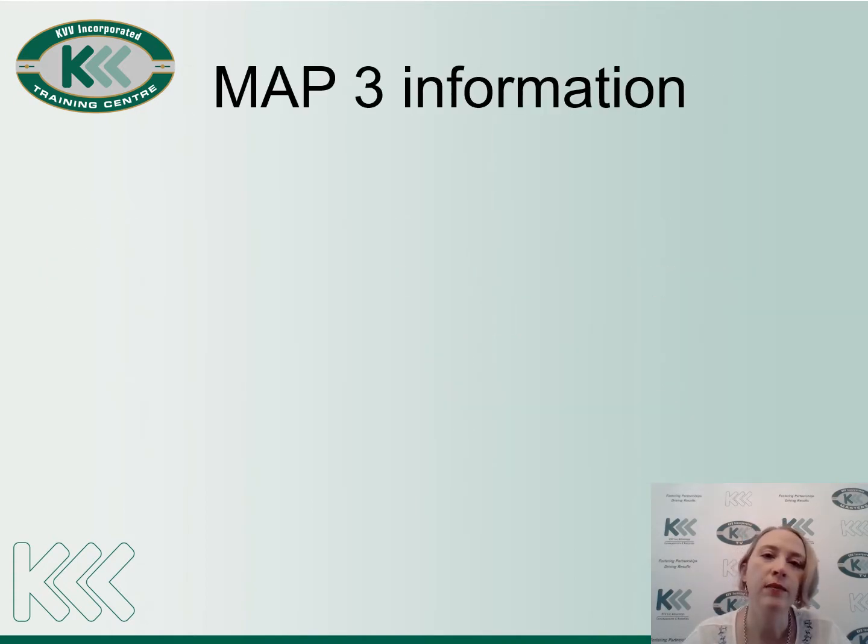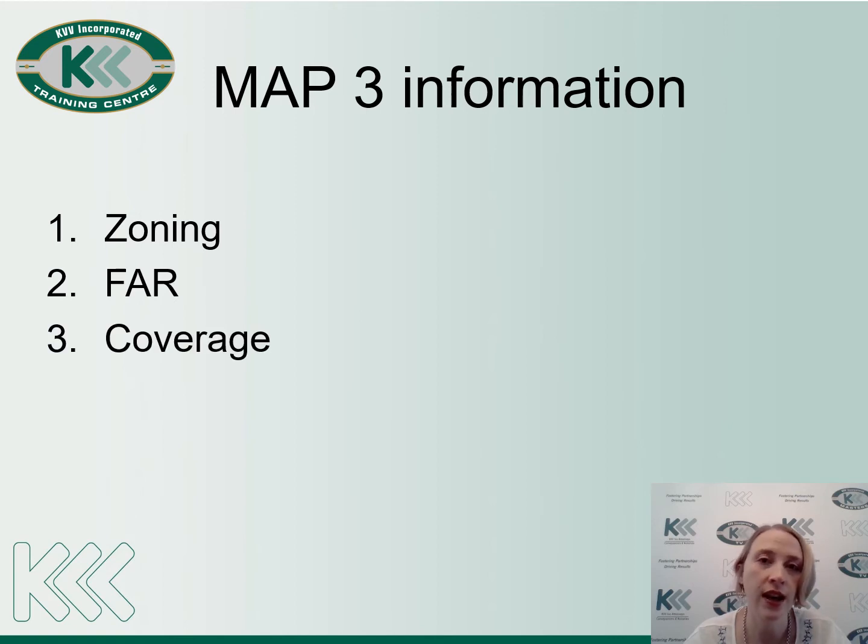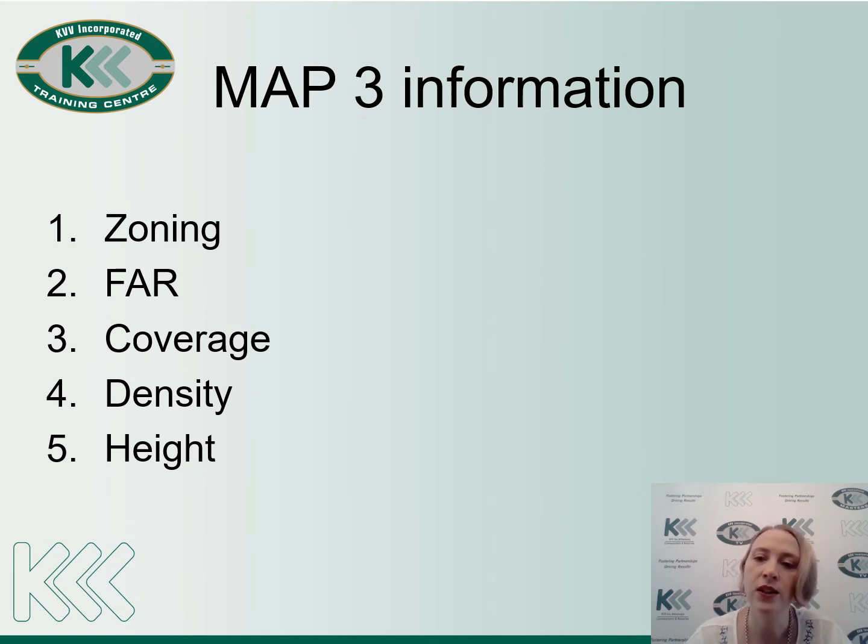Now let's look at the town planning process. Every property in South Africa falls within the jurisdiction of a local authority. At the local authority, we'll be able to see all the information that tells us the identity of the specific stand. In terms of the information at the municipality, we'll be able to see the zoning information, the floor area ratio of the property, the coverage that's allowed on the property, the density allowed, as well as the height restrictions applicable to the property. Let's look at the various points in more detail.